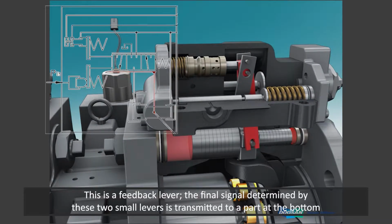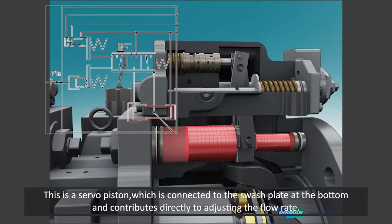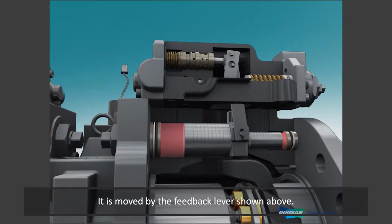The final signal determined by these 2 small levers is transmitted to a part at the bottom. This is a servo piston, which is connected to the swash plate at the bottom and contributes directly to adjusting the flow rate. It is moved by the feedback lever shown above.